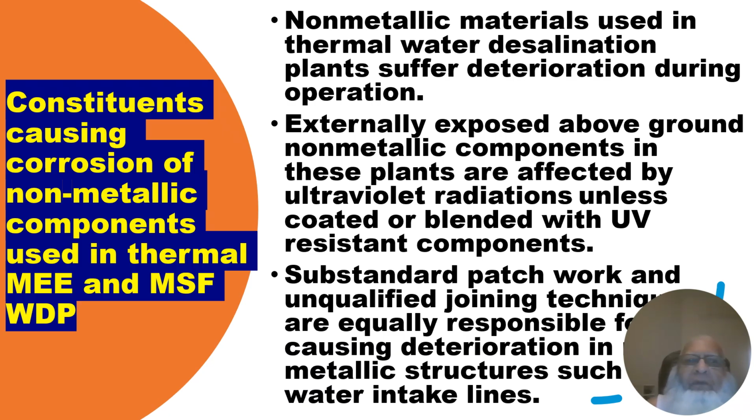Externally exposed above-ground non-metallic components in these plants are affected by ultraviolet radiation unless coated or blended with UV-resistant components. Substandard patchwork and unqualified joining techniques are equally responsible for causing deterioration in non-metallic structures such as water intake lines.